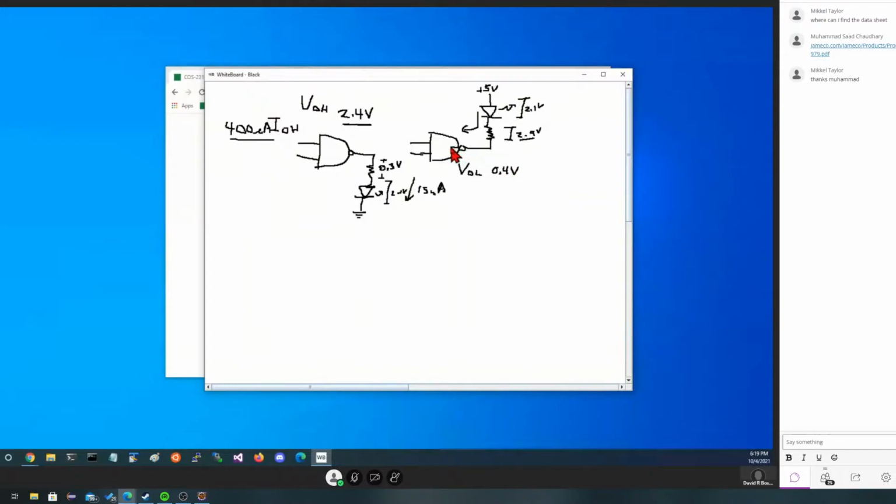And what's happening is going in and through that last transistor, there's no resistance. If you remember the picture of the gate, that simply goes to ground when it's a 0. So this is an attempt to turn it on when the 0 is asserted on the output. This is an attempt to turn it on when a 1 is asserted on the output. Design-wise, they both look okay. This one fails because of the fact we don't have enough current.